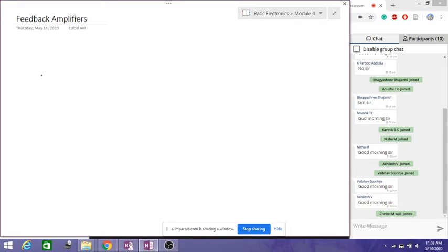Now here there is an example. It's just a basic analysis of a transistor used to switch a light on and off. Suppose we have a circuit in a common emitter configuration, connected this way, where I have my resistor here and it is connected to the collector through the LED. So this is an LED here, the emitter terminal is grounded, and here I am applying my Vin. This is the resistor RB, this is RC, and this is VCC.